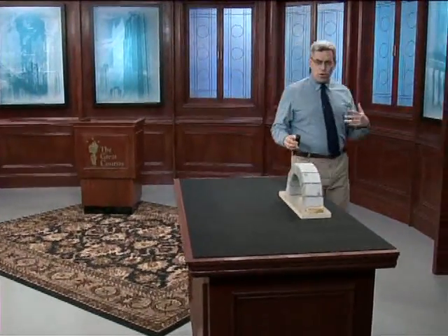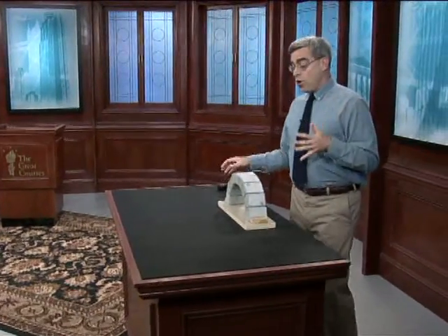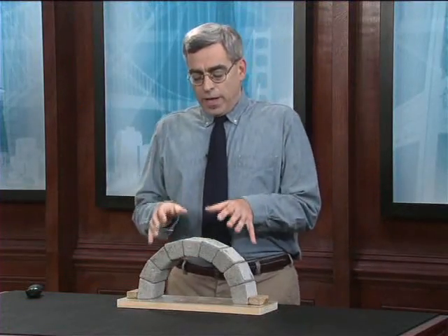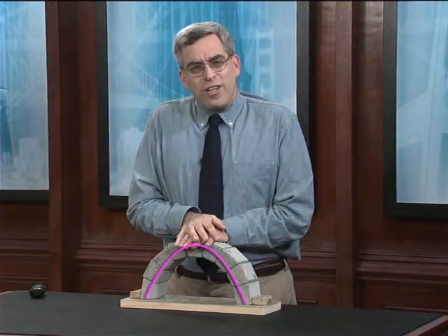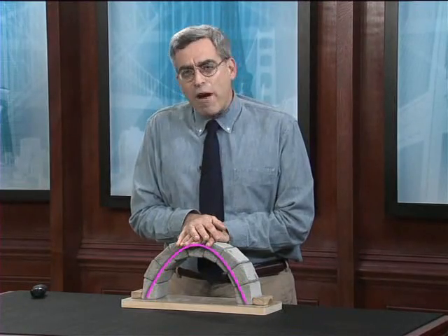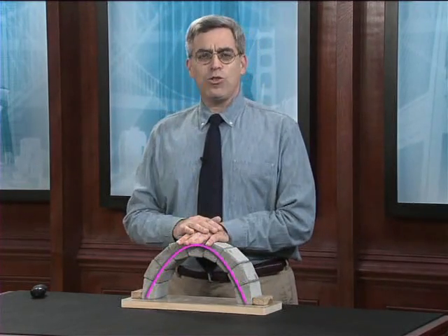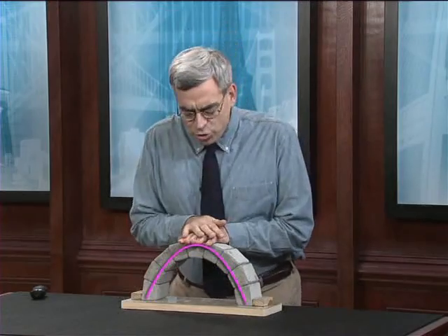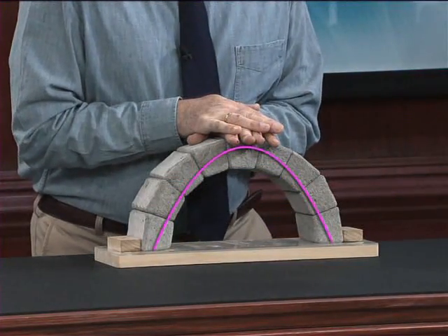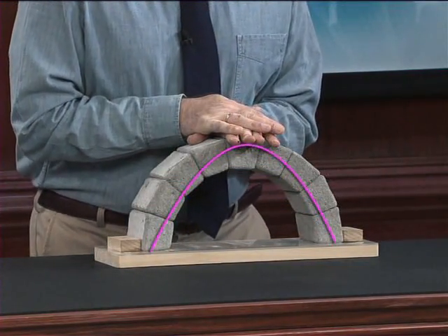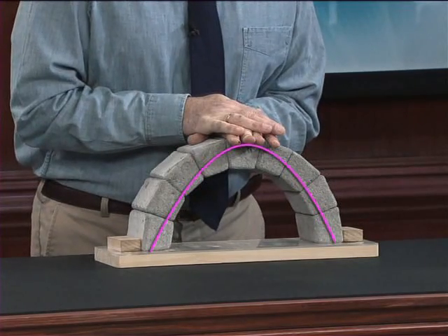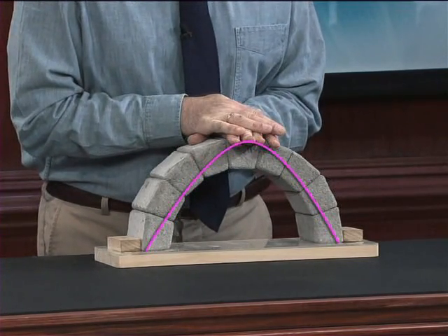The worst case situation involving concentrated load applied to an arch occurs when a very large concentrated load is applied precisely at mid-span, like this. If the magnitude of that concentrated load is relatively small in comparison with the self-weight, well, then all's well. But as the concentrated load gets larger, as you can see here, the shape of the thrust line changes. It tends more toward a triangular shape.